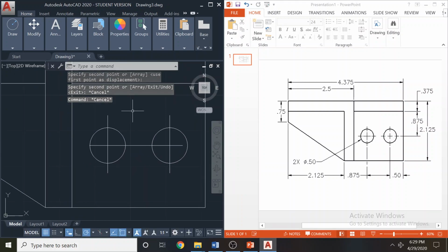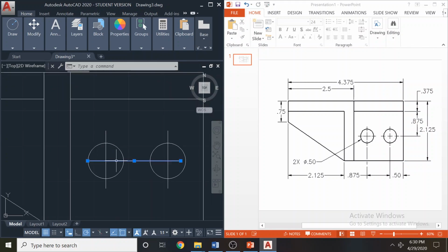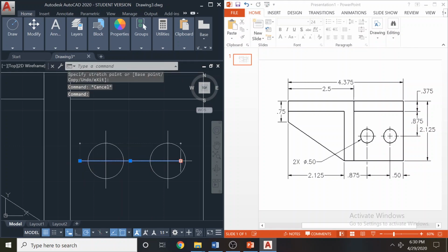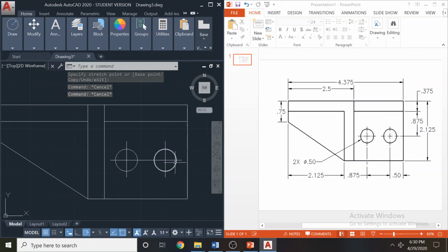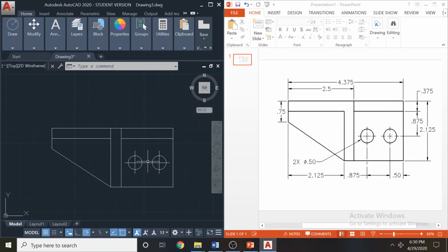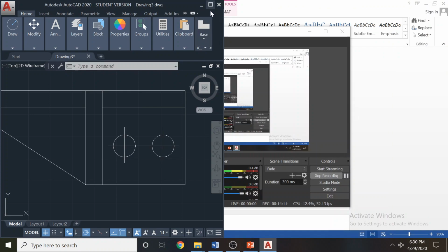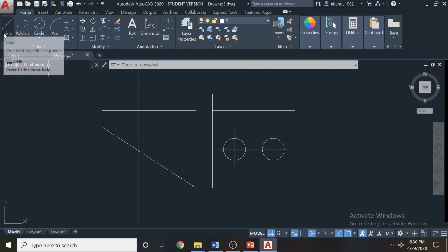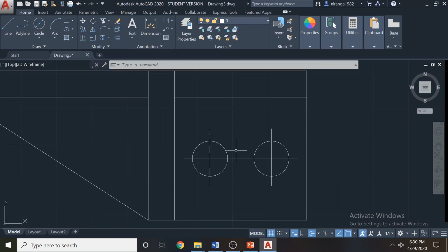So I don't have the usual center lines here. These are normal lines. We have to change these lines to center lines. So how can I change these lines to center lines? We will look at some layer theory now. You don't have center lines readily available in AutoCAD. You have the normal line tool, and the polyline tool also, which I didn't discuss, I will discuss it. Now I have a requirement to load the center lines.